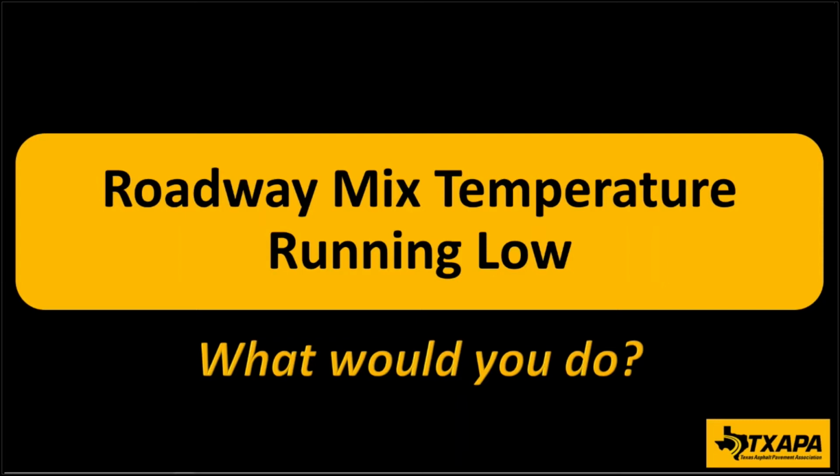Okay. All right. And Mr. Teal, what would you do? You're going to send everybody home? I would ask the 1B to get behind the paver and check it behind the paver. Okay. And keep an eye on his densities. You might have to change his rolling pattern if we do have cold loads coming in. Good. That's very good, guys.